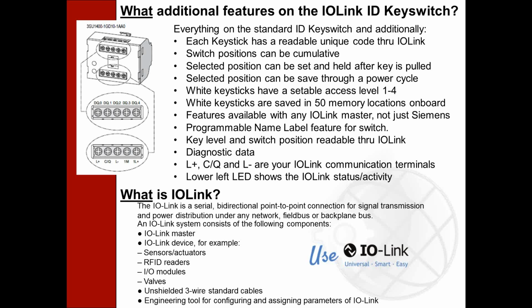The switch positions can be cumulative. I've mentioned that already. The selected position can be set and held after the key is pulled. These are all selectable features, so you have to go in through the programming tool to select some of these features. The selected position can be saved through a power cycle.